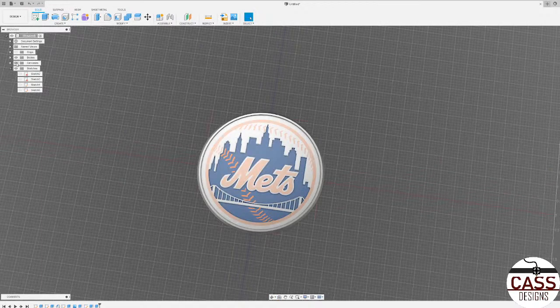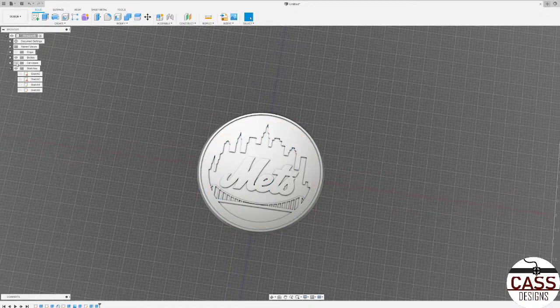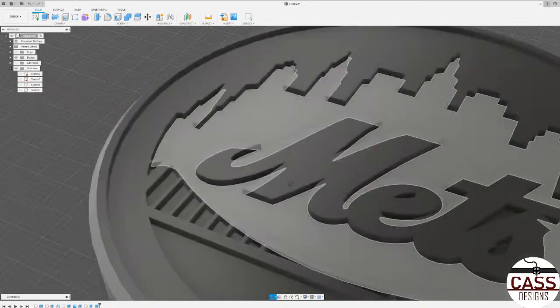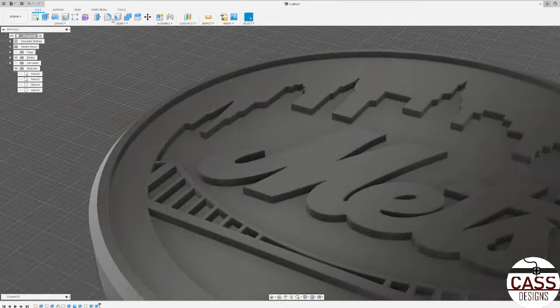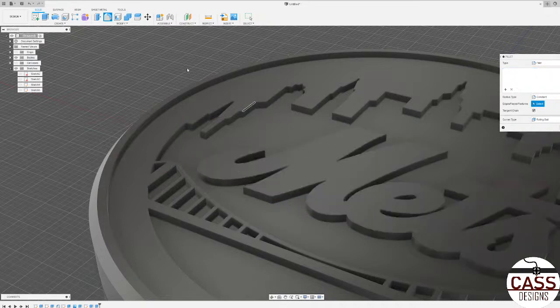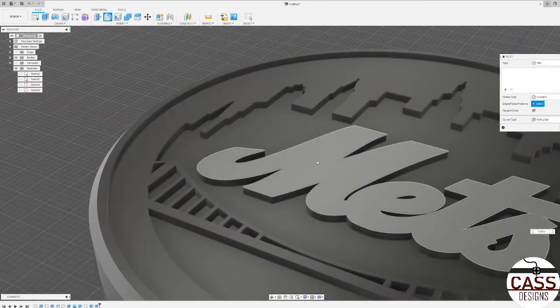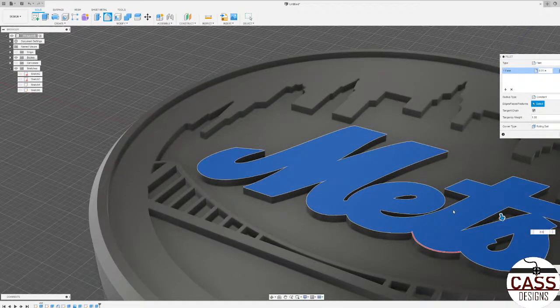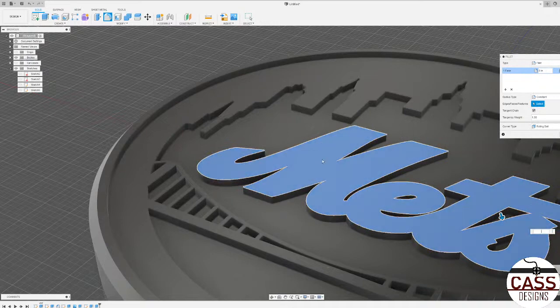Let's see. Or you know what we'll do? Let me see if I can do this. So make it kind of have that look that it had before. Actually, so if you click fillet and then you click a surface, you should select this whole surface, and if I type 0.01, does that work? No, I can't do that on this edge. So what I was trying to do is kind of fillet all the edges around this highlighted blue area.